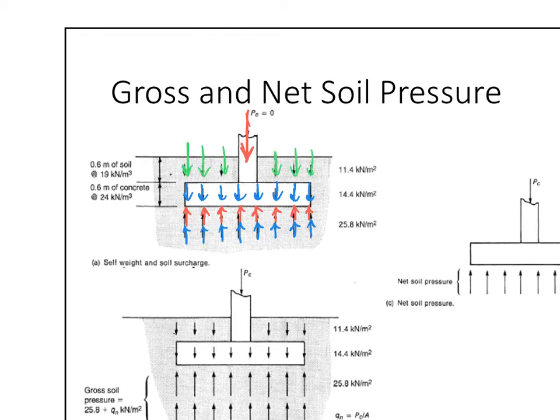Those are the loads coming from soil above the footing, from basement loads or from ground loads and people walking on the ground that is exactly on the footing, right? And that will have what? Some reaction down underneath. So now I have three colors of three reactions for three different sources of loads, right? Everybody understands how things are working here, right?